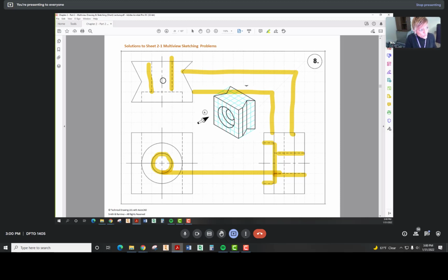Now we will have one axial center line for both of those. And it can have just one dash. But don't make these come out beyond this square. You just stop that right at just beyond the circular element. Any questions on that one?